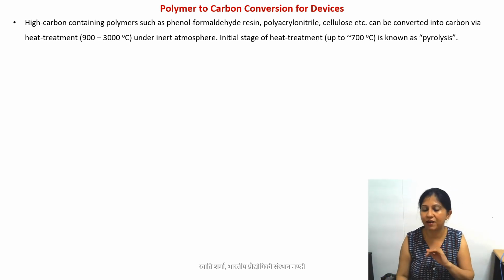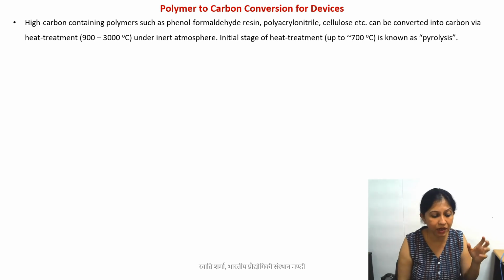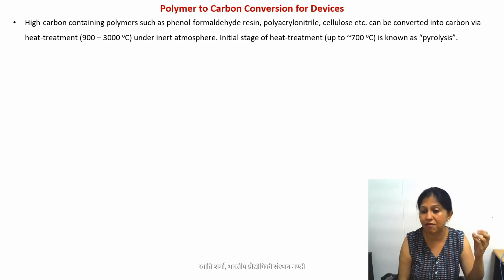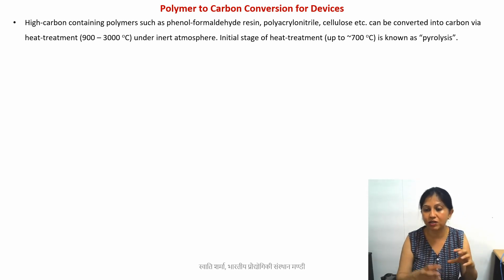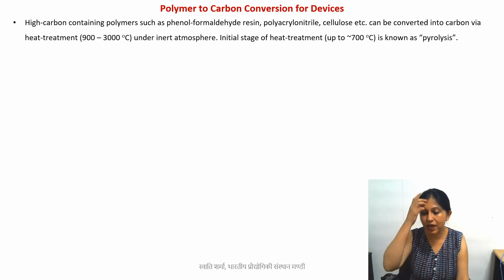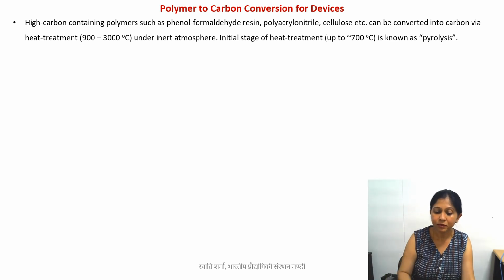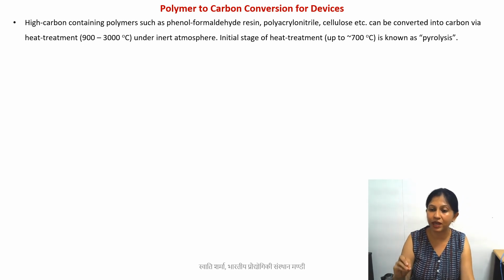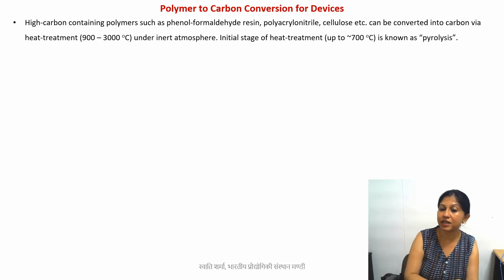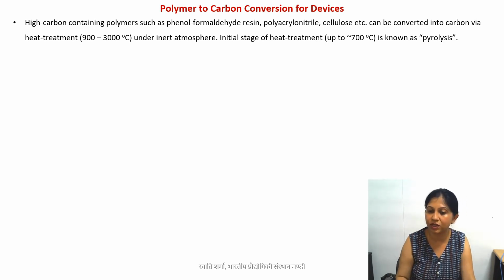Anyway, so for graphene and graphite, the hybridization state of the carbon atoms is sp2, but the materials that are bulk carbon materials, even bulk graphite, industrial graphite, will not have all sp2 hybridized carbon atoms. You will also have some disordered structures, and that is why you will call them sp2 type carbon, not just graphite. Okay. So this is important for us. Why? Because this is the type of carbon which is actually used for making battery electrodes because of its electrical and electrochemical properties. And a similar material, not graphite but sp2 type carbon material, is also the one that you have in the carbon fiber. So this is what we talk about.